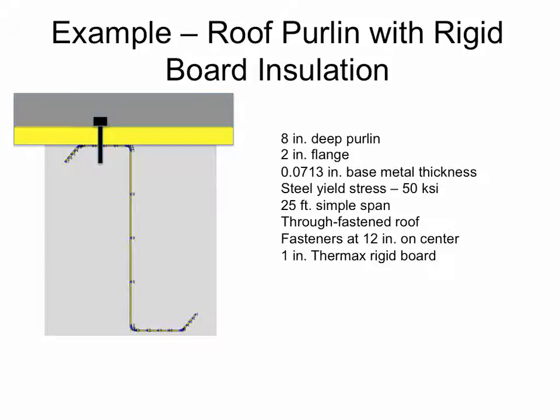Yeah, that's a great question. If we're doing nonlinear springs, then we should be doing second order analysis, like in a structural analysis program. What we're doing is just calculating elastic buckling loads, just like the Euler buckling load, but now we have some stuff attached. So that's a little bit different.